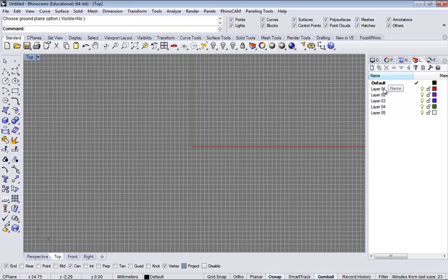So then the first thing I'm going to do is get in here and start setting up the layers. I'm going to rename one, using background BKG floor plan. I'll be in the top here, and I'm going to make that one active by double clicking on the checkbox there to make that active.